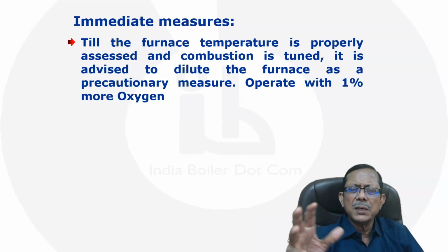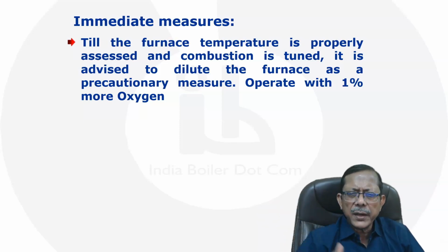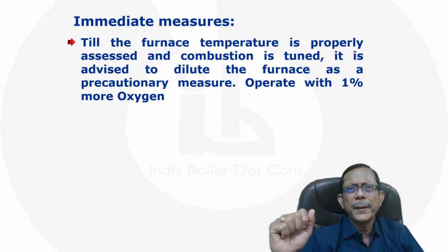Why? Because as I told you, the boiler was under design. If the boiler was under design and they are trying to increase the load, then the furnace is going to heat up naturally, right?